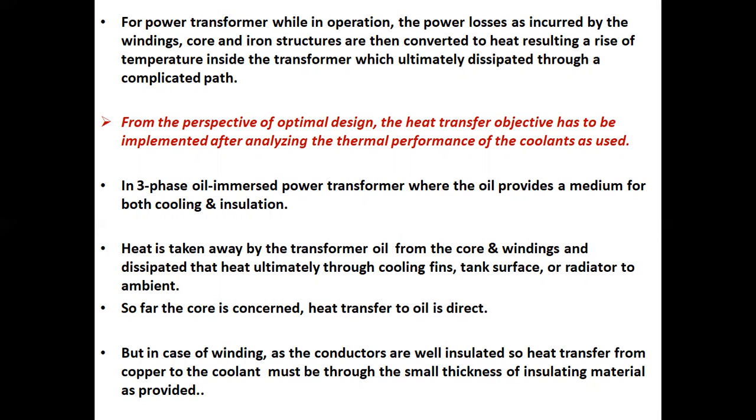In a three-phase oil immersed power transformer, where the oil provides a medium for both cooling and insulation, heat is taken away by the transformer oil from the core and windings and dissipated ultimately through cooling fins, tank surface, or radiator to ambient.